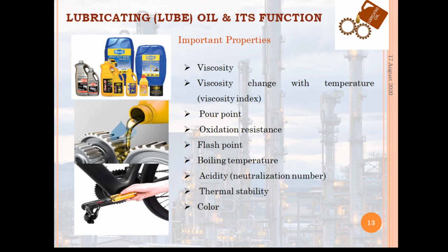The important properties of lubricating oil are the viscosity, the viscosity index, which means the viscosity change with temperature, the pour point, oxidation resistance, flash point, boiling temperature, acidity, thermal stability, and color.